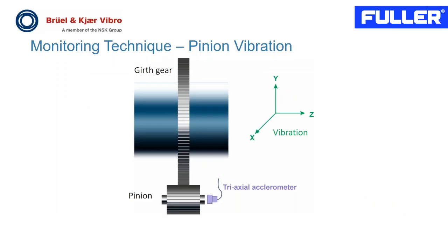So we talked a little bit about the radial wobble and axial displacement of the girth gear and how it's monitored. And now we're going to talk about monitoring the pinion. There can be 1 or 2 of these driving the girth gear. Now, the rigidly mounted pinion, driven by a motor and a gearbox, is basically monitored by accelerometers mounted on the bearing casing, just like gears in other machines, except there's a need for special considerations to be taken in this case because of its very low speed. For this, special sensors are needed together with special monitoring techniques and signal processing.